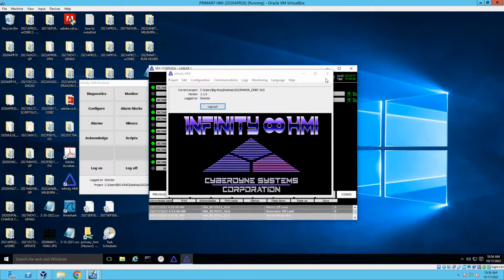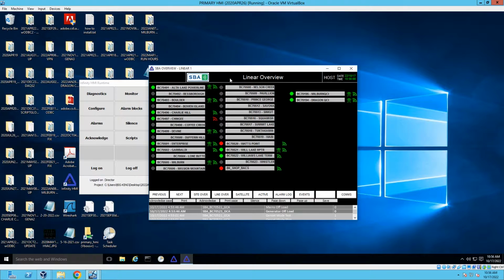Here we have our opening screen, and I'll point out a few features that are important whenever developing host screens. First, the medium contrast ensures that our network operations center operators are not straining or becoming fatigued during their shift. Next, the use of red is limited to alarms, failed states or items potentially requiring action. We will note the host date and time is always in the upper right corner.